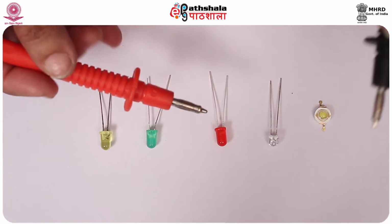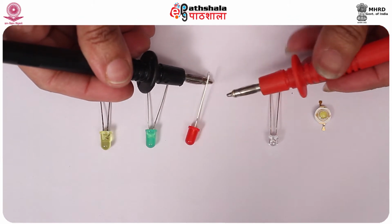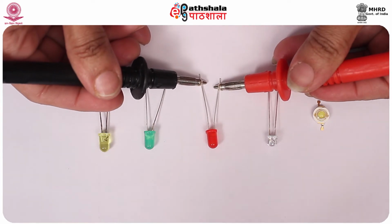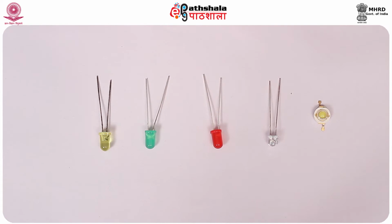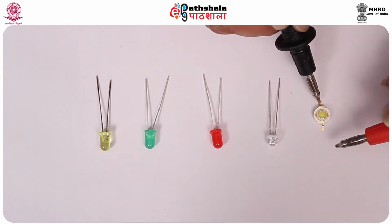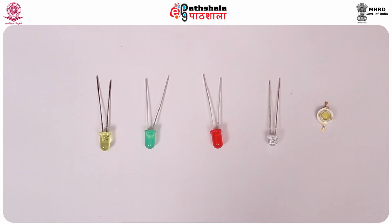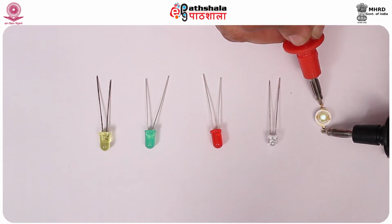You can verify that if I reverse these two terminals, light will not be emitted. That means this is reverse bias of LED. So from this one can find out which one is cathode and which one is anode. Same you can see over here. This is reverse bias. This is forward bias.